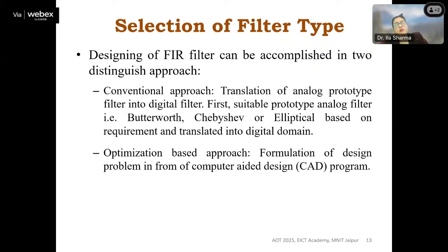So based on the different window functions, they have different shapes that are being multiplied with the sequences, and the outputs are being filtered out. This was the conventional approach. And then we have the optimization based approach, where the formulation of the design problem or the objective functions are there, and computer aided design methods are being used to design the filter.